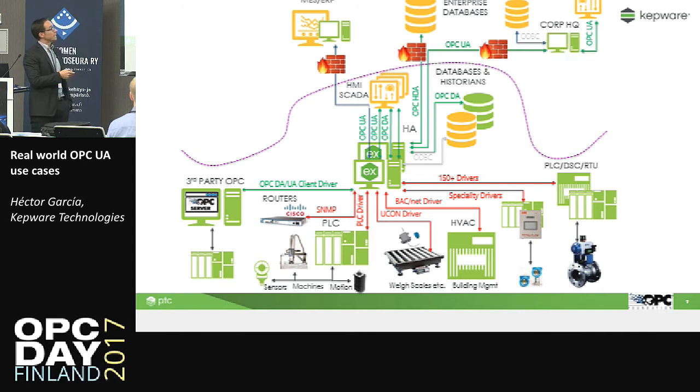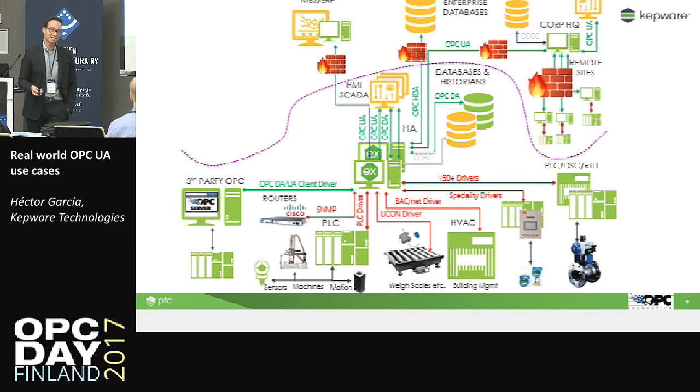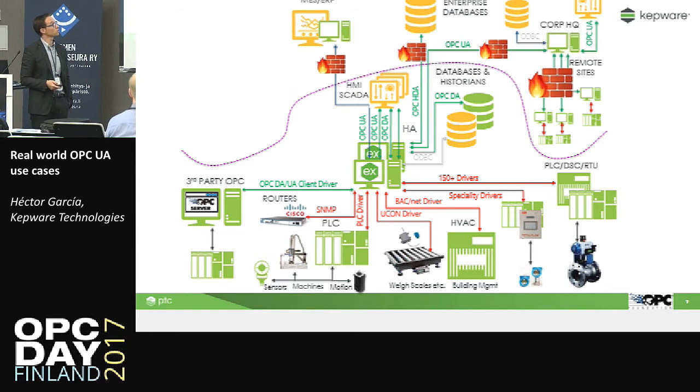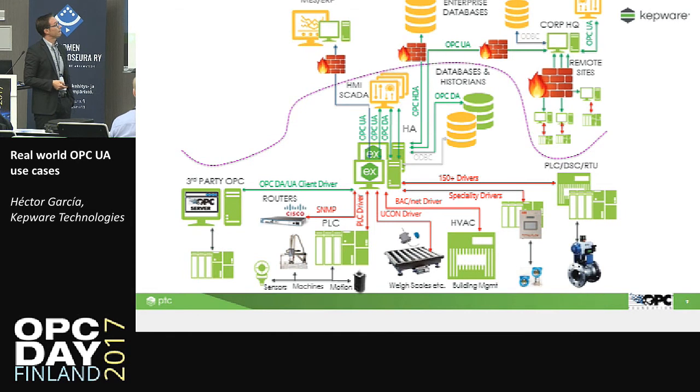And we may not have only one plant. We may have many different plants, many different sites, all of them sending the information to the corporate SCADA. That corporate SCADA can be installed in the cloud, which, by the way, is quite common nowadays.